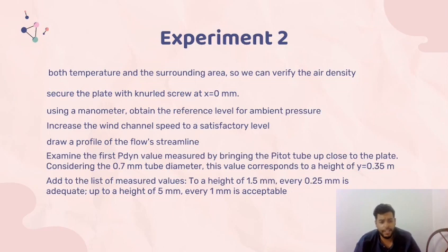And finally, add to the list of measured values up to a height of 1.5 millimeters. Every 0.25 millimeters is adequate. Up to a height of 5 millimeters, every 1 millimeter is acceptable. And the final step is to repeat this in the different area.